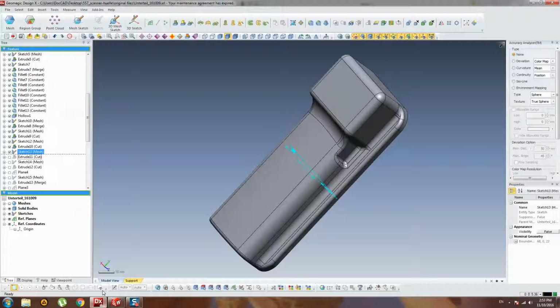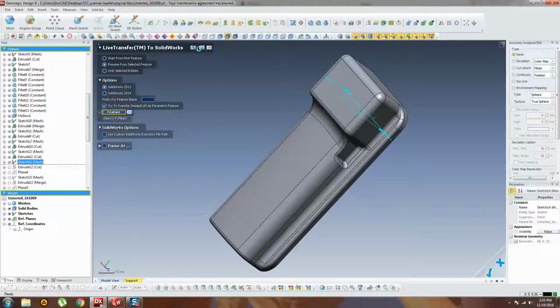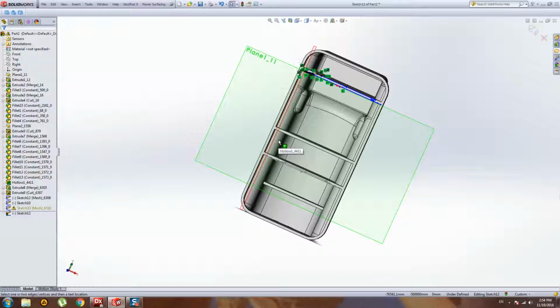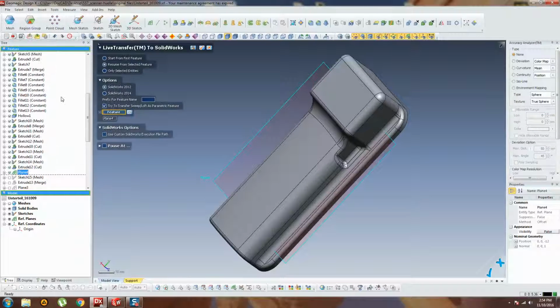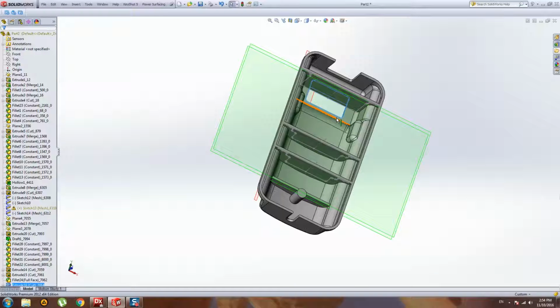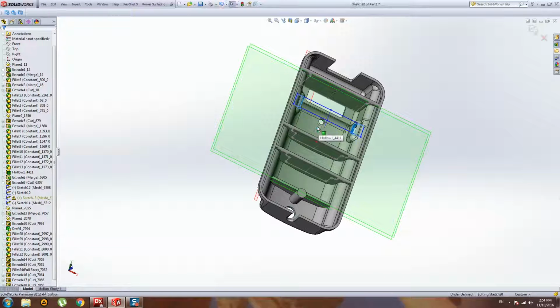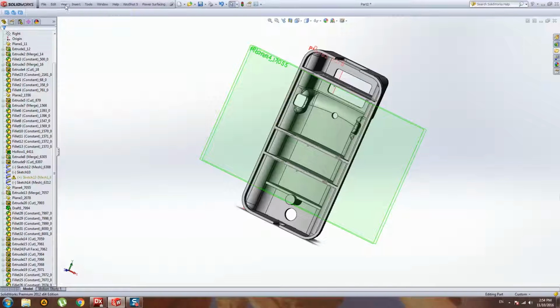Yes, I understand the problem. It can't build the cutting element, extrude cut. We will only build sketches for these elements, and resume in Geomagic Design for the SolidWorks transfer. Next. Next. Oh, everything fine now. All features were built well. And the system tells about successful export.